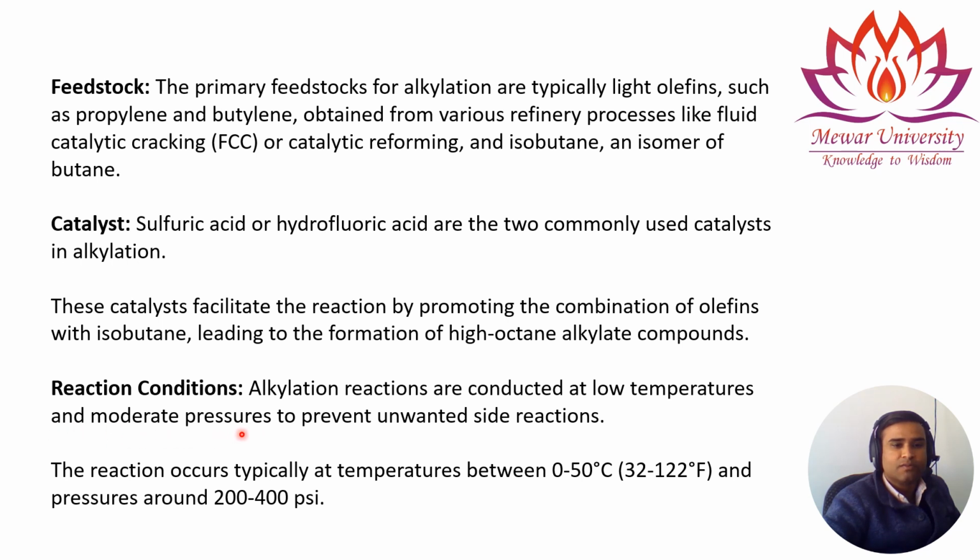The pressure is moderate to prevent unwanted side reactions, cracking reactions basically, because we are combining low molecular weight olefins. The reaction occurs typically at a temperature between 0 to 50 degrees centigrade, or 32 to 122 degrees Fahrenheit, very low temperature, and pressure around 200 to 400 psi. This is also very low pressure.